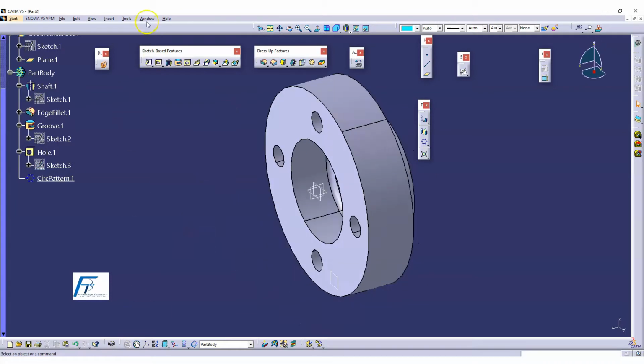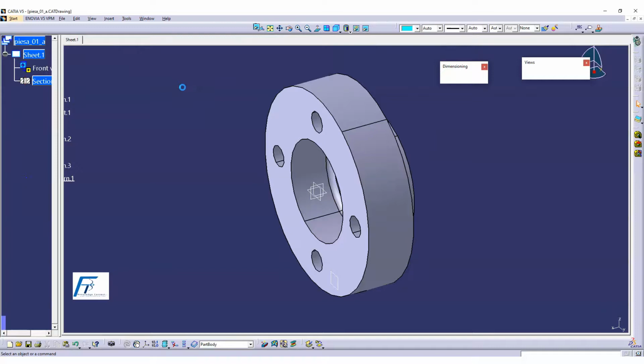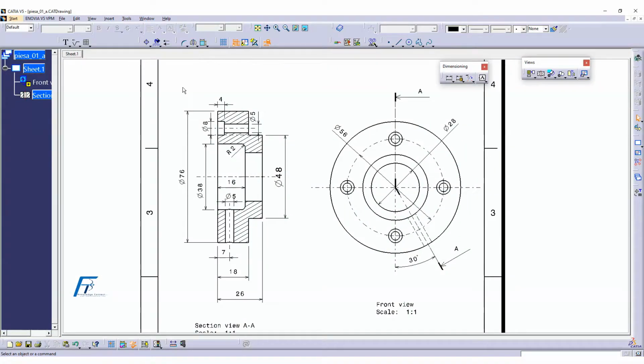So if you see the drawing, as per the drawing, we have just understood how to read a drawing first. We understood how we made the decision of making a circular shaft. So we decided the profile, right? And then we did this hole, which is at a distance of 7 mm from the top face. And then we decided, okay, let's create 4 holes of the dimension 8, 4 and 5 mm, the counter bore, and we created this one.